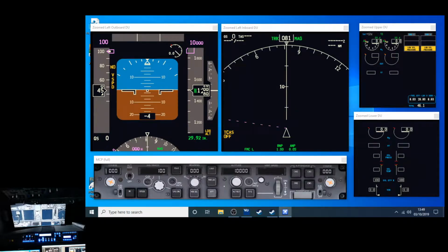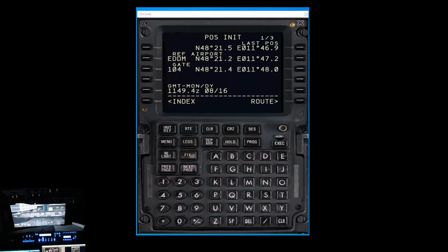There we go. Now once the GPS is aligned, it puts our position here on our main instrument panel. Right, we'll go back to the CDU or FMC and continue through the process of loading in our flight plan. So we turn off the instrument window now and just bring up our FMC. There we are. It's very convenient in that it gives you the steps on the next part of the index here. So we need to put in our route.